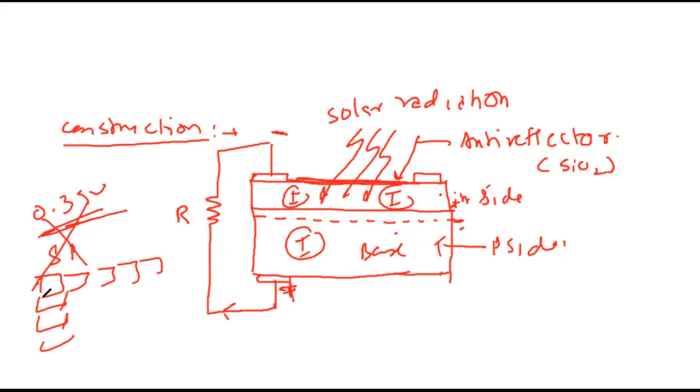The N side, P side are joined together. N is towards the exposed surface and P is the base. When light is incident, due to absorbing energy, the covalent bond breaks. Hence, a positive negative pair is formed. P is earlier negatively charged, so it will pull all the positive holes, get neutralized and become positive. N pulls the negative electron, gets neutralized and becomes negative. So at its ends, we get negative and positive potential. When a wire is connected, it supplies current through load resistance.